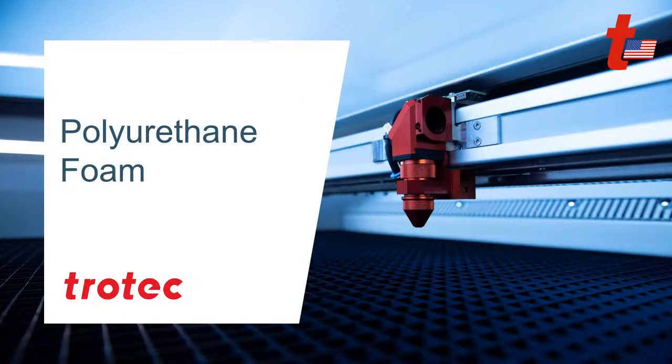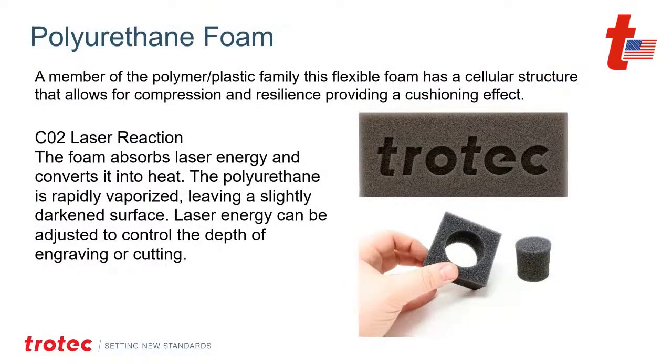Okay, moving on, polyurethane foam. This is a very popular laser-friendly material that I like to work with. Polyurethane foam is a member of the polymer plastic family. A flexible foam has a cellular structure that allows for compression and resilience, providing a cushioning effect. CO2 laser reaction: the foam absorbs the energy of the heat, basically vaporizes the surface of the material, and produces a clean, controlled depth engraving and cutting of the material.